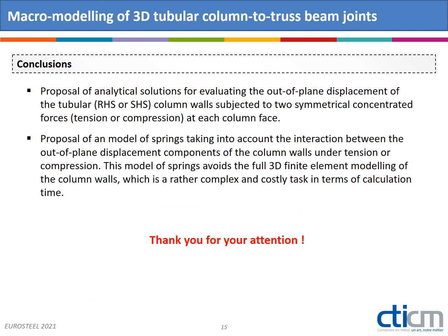Now I finish my presentation with two conclusions. We proposed an analytical solution for evaluating out-of-plane displacement of tubular, rectangular, or square hollow section columns subject to two symmetrical concentrated forces, tension or compression, at each column face. And we propose a model of springs taking into account the interaction between out-of-plane displacement components of the column walls under tension and compression.